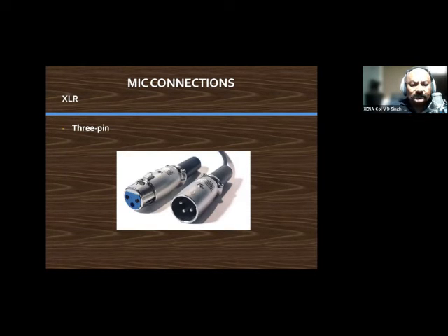Most of the microphones, professional microphones, are using this. The beauty is that this reduces noise. There is line noise whenever you're connecting your microphone to the amplifier or preamplifier. So cables are quite amenable to certain types of noises. So noise cancellation takes place, and this is a very, very high grade connector, the XLR or 3-pin connector.